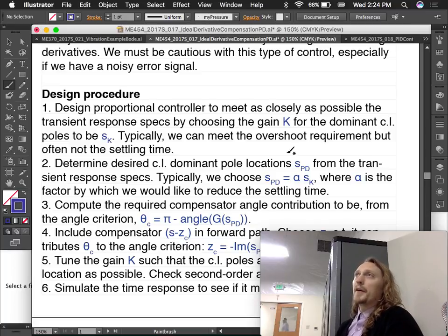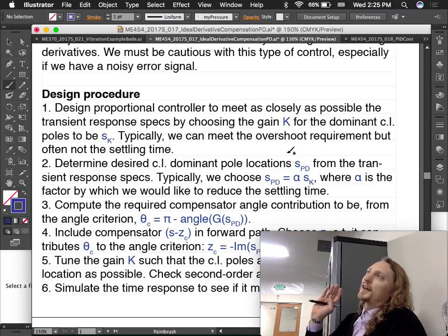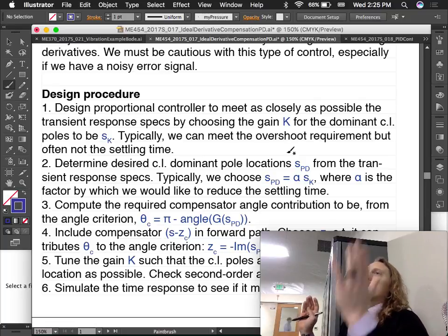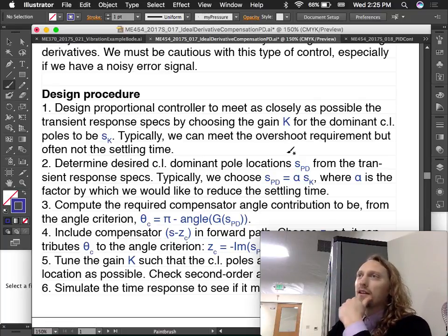So I recommend two things. Assuming it, pretty much your design tools require you to assume it in these cases. But then you can check in the end. Like you can check whether the two poles are at least, I guess, five times farther than the next pole.